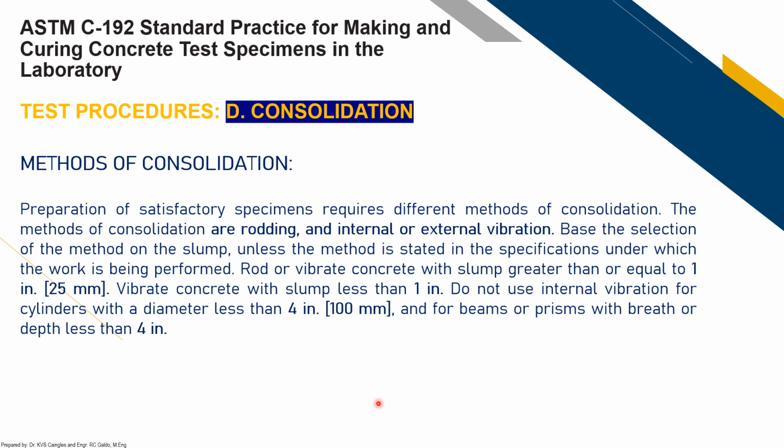We do consolidation to get rid of those voids that are inside your concrete mixture, because it is not ideal to have voids within your concrete mixture as it would affect not only the strength but also the durability of your concrete. For methods of consolidation, it can be done by rodding, or internal or external vibration.